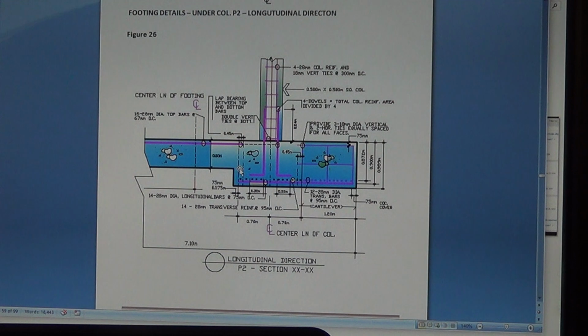And this is an architecture style of layout. Same thing there, but I just avoid cutting it. The bottom bar here is cut there in this architecture drawing that I do. And for civil engineering, we don't cut it. It's from here and goes all the way up to the top of the midsection of the combined footing.